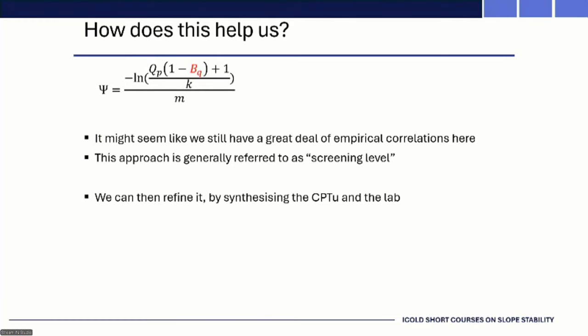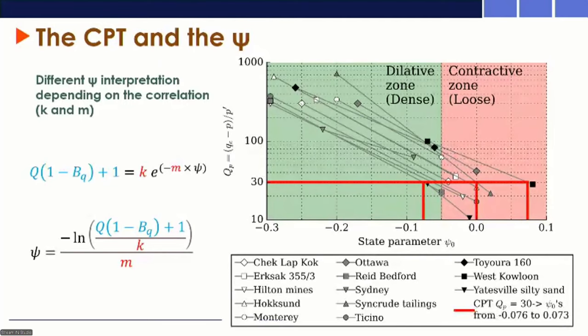Then we can use perhaps laboratory data, CPT and cone penetration data. So this is something I put in. It's not in the original slide package, but I think what you're getting does include it. So now we've got state parameter from, again, a bunch of calibration chambers on the horizontal axis. And again, you can see very few in the positive state parameter range.